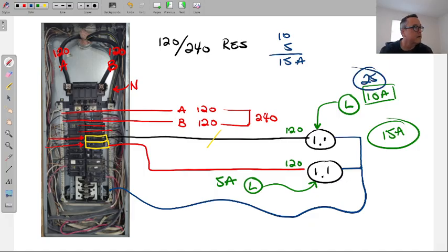Say 25 amps. Well, this 20 amp breaker now is going to trip. It's going to open that circuit up and cause, at the very least, power to shut off, the load to stop putting all that amperage onto the circuit, and things to shut off.